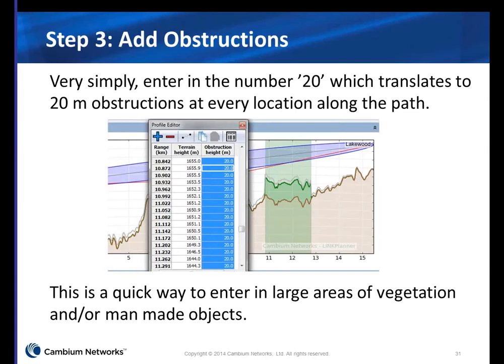We use at the moment the SRTM dataset, and this will include a little bit of the height. If you've got large areas of contiguous buildings, then when the radar returns the data, the height may be incorporated. If it's very isolated buildings, the heights are unlikely to be incorporated.